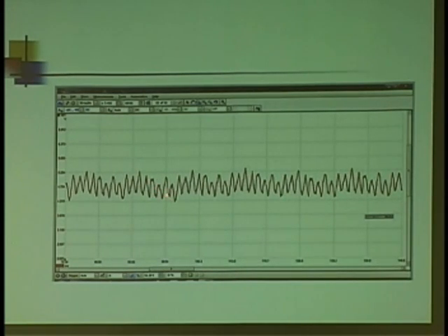Now notice I do have a couple of weak points. There's one, then there's one. There's one, there's one. And they repeat, don't they? They still have a pretty nice sharp edge to them though. And think about what it is that I'm looking at. I'm looking at the current peaks inside this fuel pump motor just like I can any other motor, and the amount of current it takes to turn that through. I'm looking at the current going through a brush, through the commutator segment, through the winding, and then back out again.